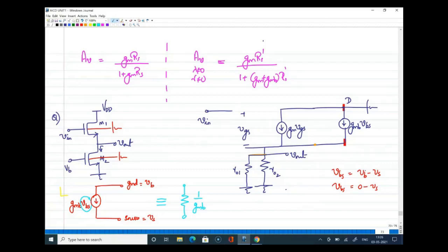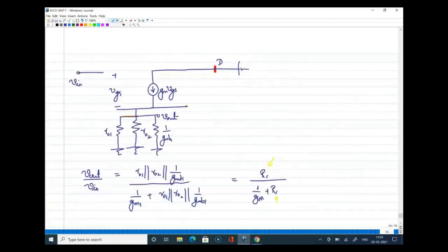But having said that, if you are asked to write the voltage gain expression for a question like what you can see on the screen now, and you directly write 1, I'll appreciate that because you identified that it is a common drain amplifier. But you may not get marks because what we are expecting by giving the circuit diagram is to arrive at this kind of expression. So after writing all this, if you equate it to 1, that is perfectly fine. Is it clear, Sri Harsha?